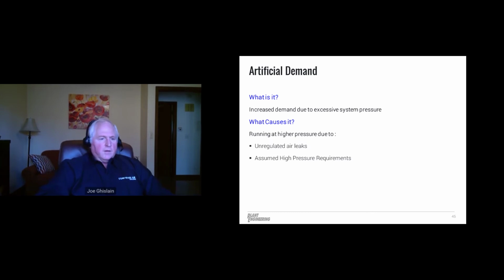Artificial demand. That's the next one I want to tie into a bit. What is artificial demand? It's increased demand due to excessive system pressure. What causes that? Running at higher pressures due to unregulated air leaks, so any supply air leaks. So again, we're back to maintenance, and any assumed high pressure requirements. What does that mean? Well, you may have a piece of equipment that is a high pressure application that is a small percentage of the load, but it's driving you to run the entire system that high. And when you run the system higher, what happens to air leaks that aren't regulated? They leak. And even regulated ones, when the regulator's cranked all the way down, leak more. All of them leak more with higher pressure. The higher the pressure, the greater the leak.